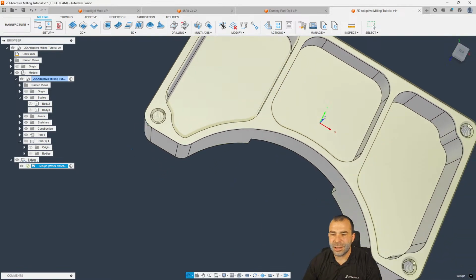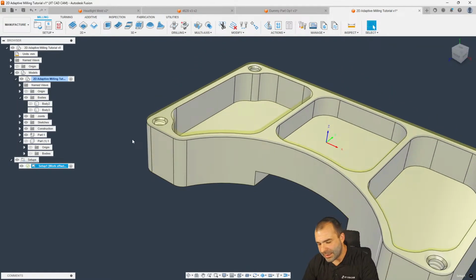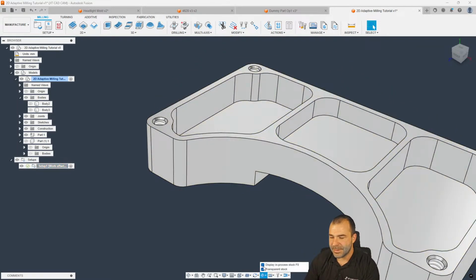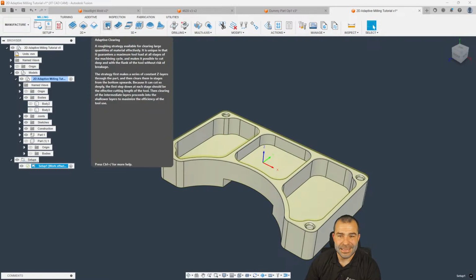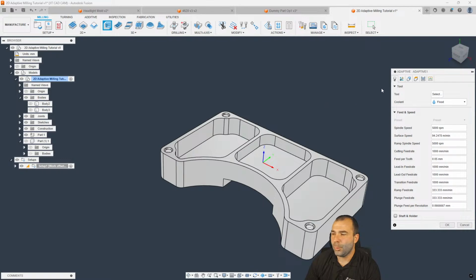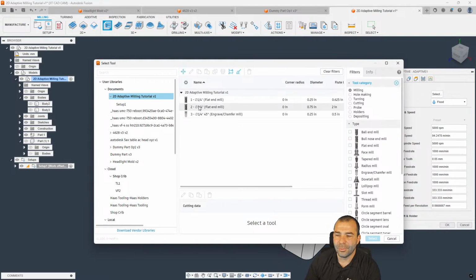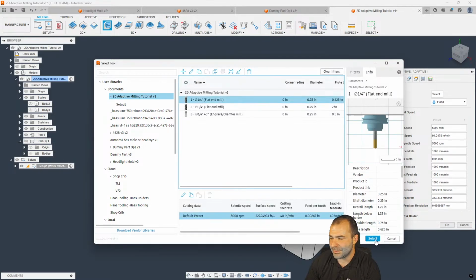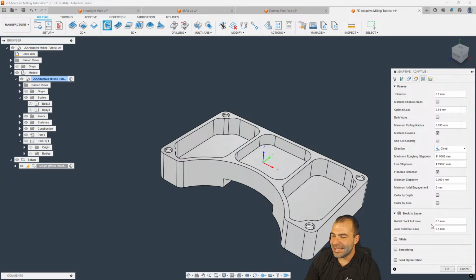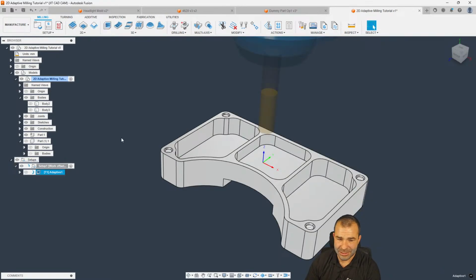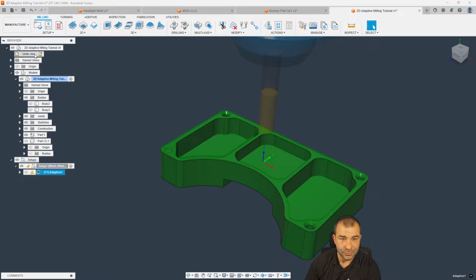So if I was to go in and machine this part, I'm going to go ahead and hit F8. Let's make sure our stock is turned on. Okay, cool. So going in and doing something like adaptive clearing, for example, it's automatically referencing where our stock is versus our part. Now, in this case, you guys may criticize me a little bit because yours truly only put 20 thou material everywhere. So I need to actually change my radial and axial stock. I also need to go ahead and scratch my head because this needs to be changed over in what we call bald eagle units. There we go.